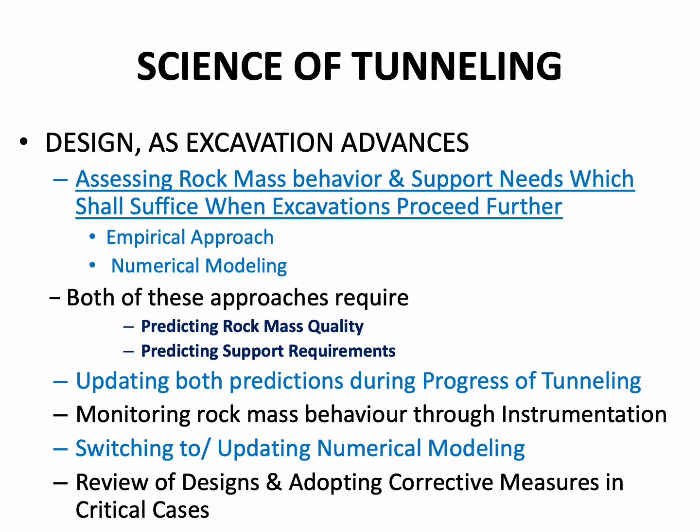Thus, the science of tunneling is design as excavation advances, assessing rock mass behavior and support needs which shall suffice when excavation proceeds further, either through the empirical approach, and if the empirical approach becomes redundant, then resorting to numerical modeling.